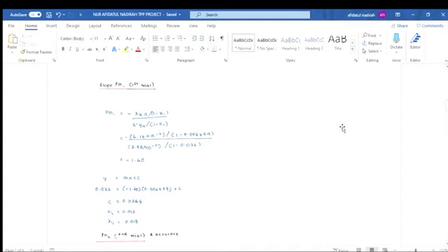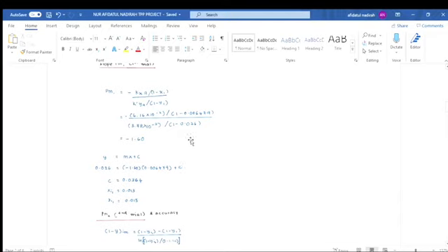Next, we move to the next step, which is to find the slope by using the equation of slope of a packed absorption column. This is the quick equation, which is negative k prime xa divided by 1 minus x1 over k prime ya divided by 1 minus y1. The values of k prime xa and k prime ya are already stated in the question before. For the values of x1 and y1, we can get them from the graph, which we already got in the previous step. After we substitute the values, we get the slope is equal to negative 1.6.